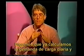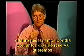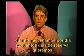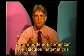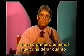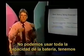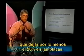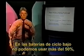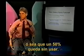Given the fact that we've previously calculated our daily load demand, so we know how much we need on a daily basis, and how many days of reserve we want to get us through an expected period of bad weather, we can now begin doing the mathematical calculations for battery sizing. The way we do this is by first considering how much of the battery we can use. We can't use all of the battery capacity. For deep cycling types of batteries, we can only use up to 80%. We want to leave at least 20% on those plates unreacted. For more shallow cycling types of batteries, we can only use up to 50%. So 50% remains unused.